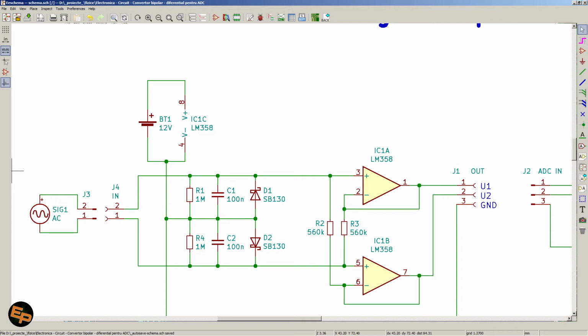It can be higher, it can also be lower, but be careful about what we're putting here, because this will present itself as the input impedance for whatever circuit we are connecting to its input. Okay, so it cannot be too small, otherwise it will start drawing too big a current from the input device in the input circuit, and that circuit might have a problem, and we might overall have a wrong reading.